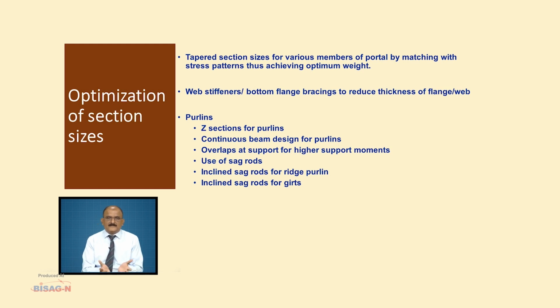So, this is the basic design philosophy as far as the design of PEB structures is concerned. Remember that a PEB structure will be economical only if you achieve this optimization intelligently using the technology without compromising the structural requirements. People generally tend to provide a lot of redundant members which are not required. These can be taken out. You can have a number of iterations using the latest software and achieve the optimization. Then and only then will the PEB be an economical option compared to the conventional one.